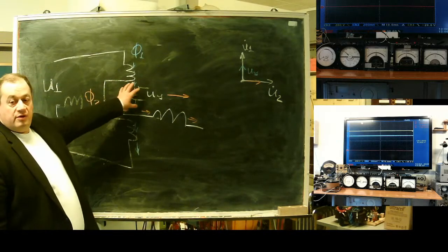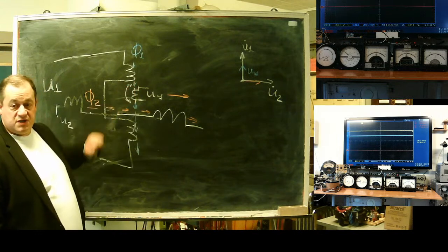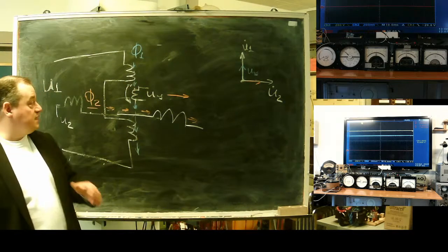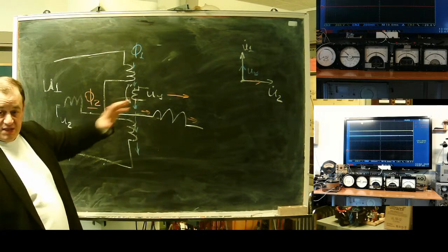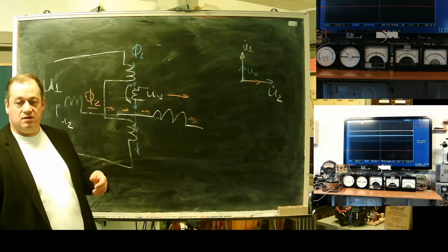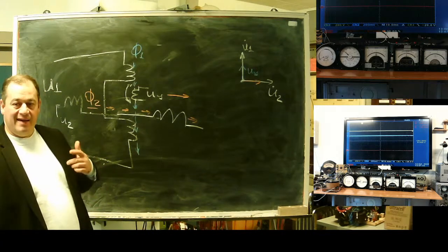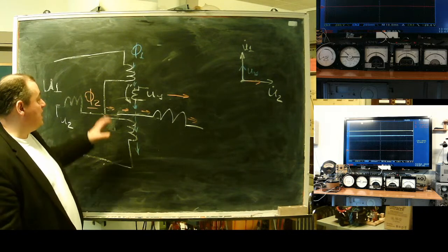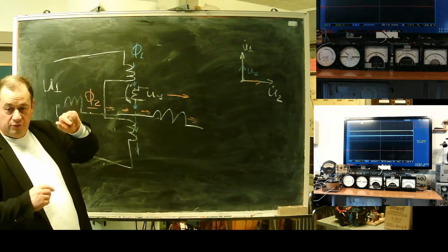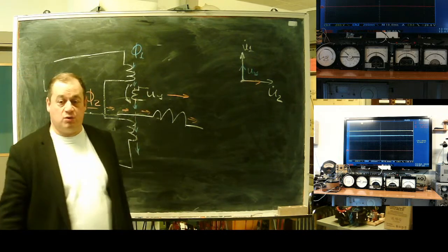So with rotation of this coil, changing its angle relative to the system base, I can have any angular shift between the network of first and second voltage and the output voltage of this coil.